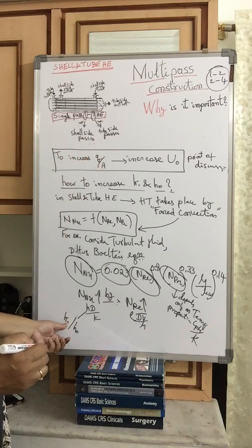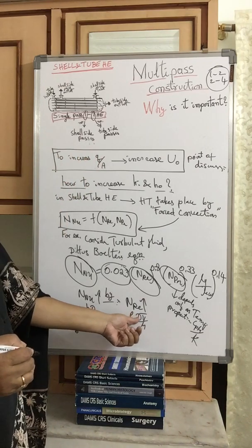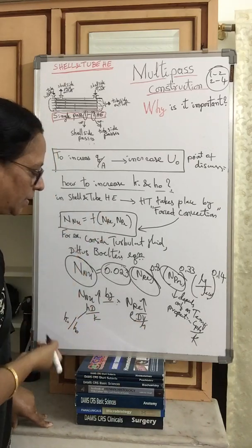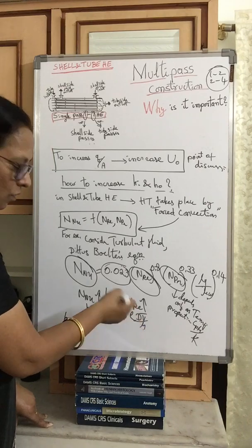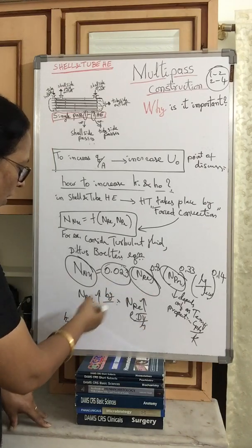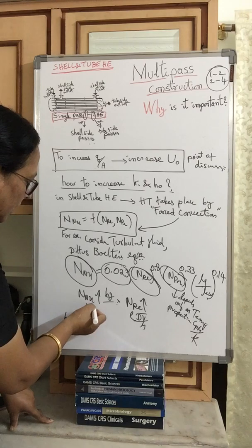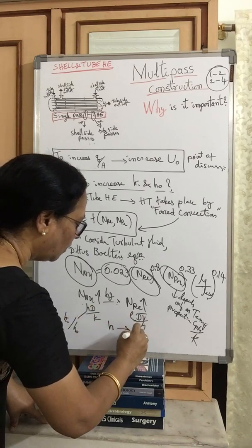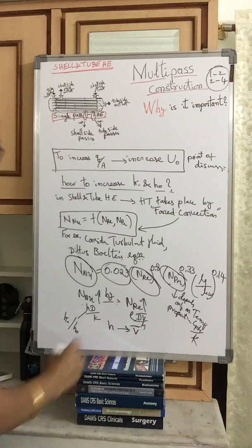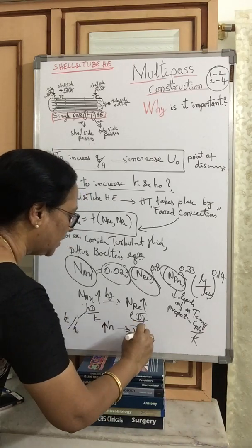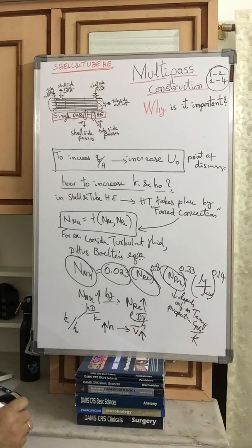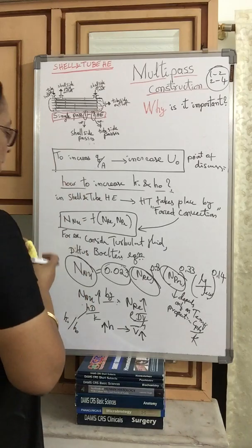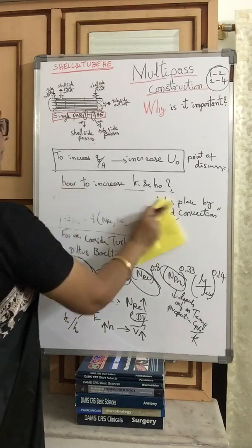If you write Hi, this D becomes Di. The diameter is fixed, and the properties depend only on temperature. So K is fixed, D is fixed. So h depends only on velocity. So h can be increased if you increase velocity. That is the concept. So what we have understood here.